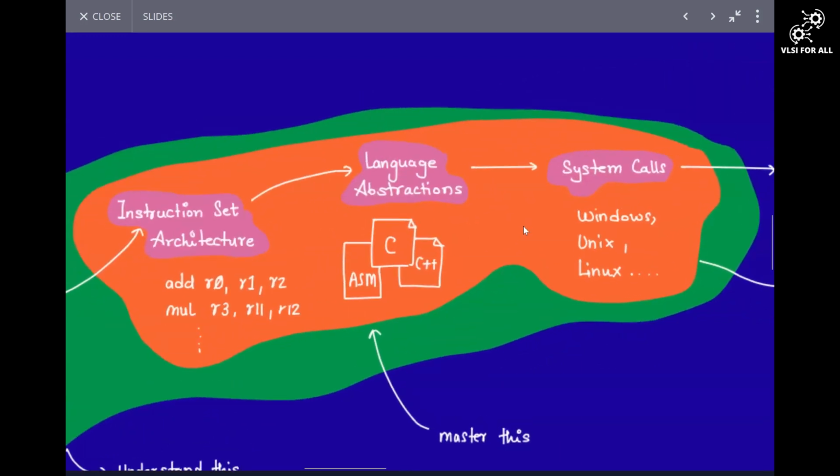If you want to implement any part of the code efficiently, sometimes you may write some of your programs only using assembly for that hardware, so that it can efficiently process your program, right? There might be a need here and there to diverge from C for some part, write in assembly, and get back to C, so that you can run that part efficiently. You don't want your compiler to convert your program and make it worse. Sometimes you only want your set of assembly language instructions to run on the processor. In that case, you should also know what instructions are available for that processor.